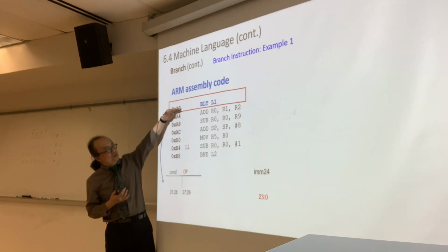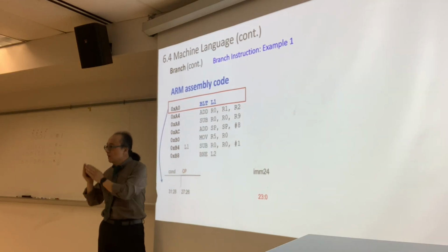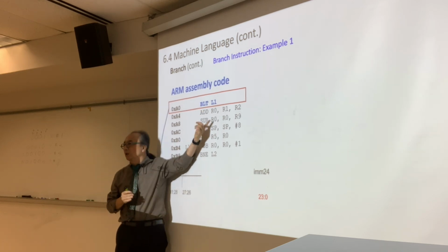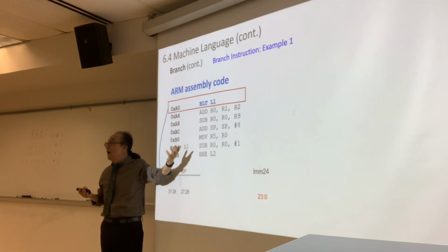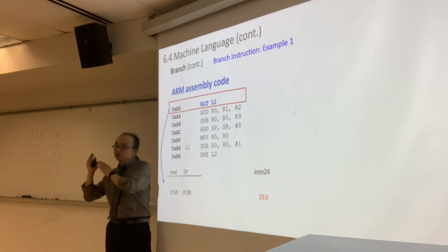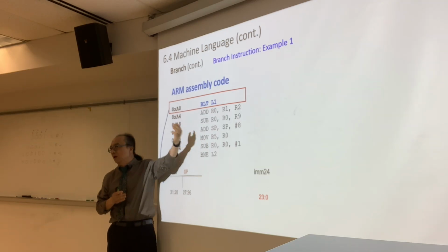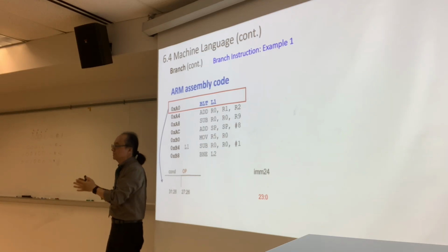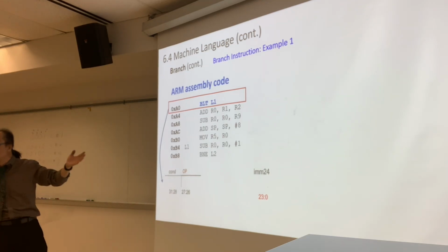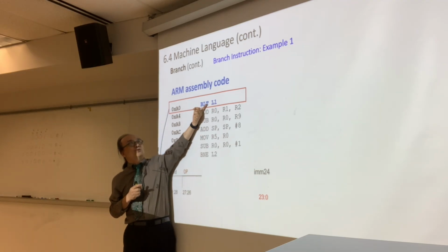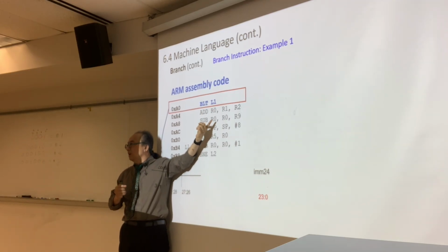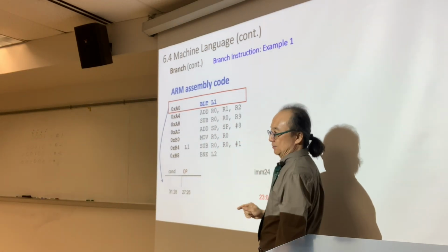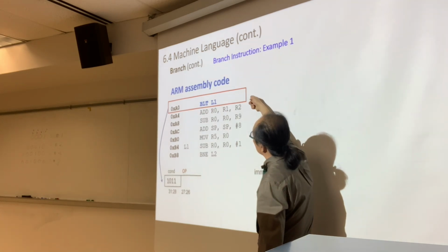Whenever we are executing a series of these instructions, we feed in the process. In the single cycle, we're going to execute one at a time. But typically our machines are pipelined machines. So we just feed in all of these instructions, actually 5 instructions at a time. We can execute them because there are 5 stages of pipelining in ARM architecture. So whenever we are executing any given instruction, the PC, program counter, is going to point at that instruction. So right now, PC value is right here.